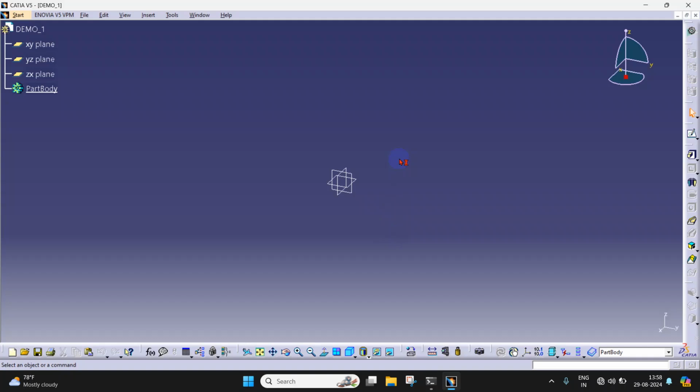Okay. Now, in order to enter into the sketch mode, we have to go for a sketcher icon here. You can see on the right hand side, a label appears there, sketch. So click on that icon. And now you have to select any of the three planes available in this triad. Either you can choose this plane, or this plane.